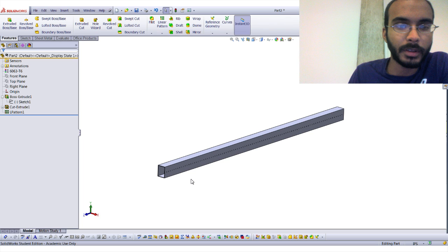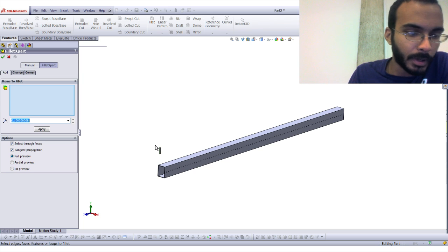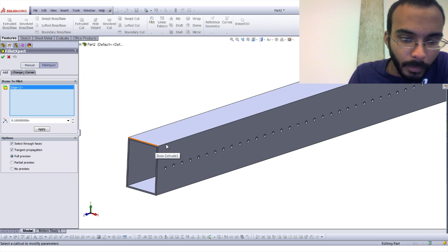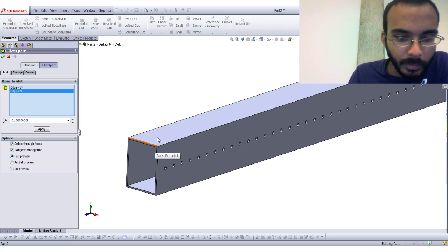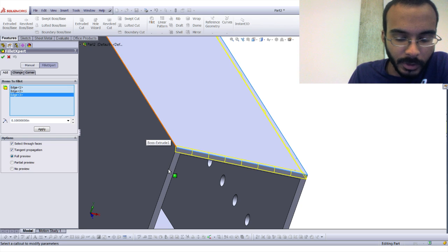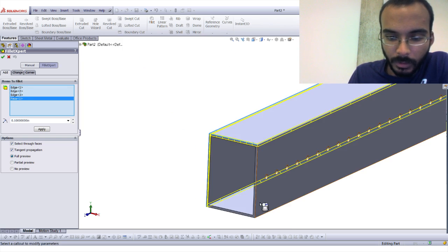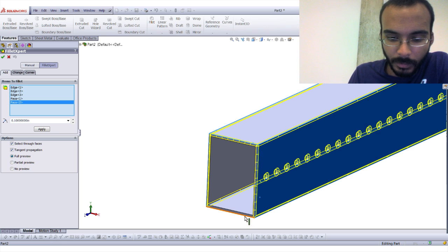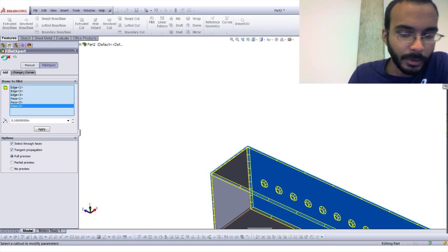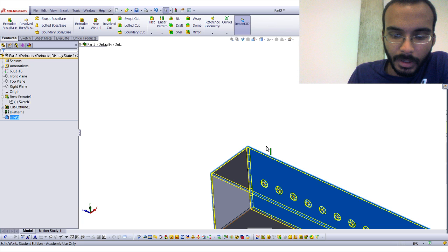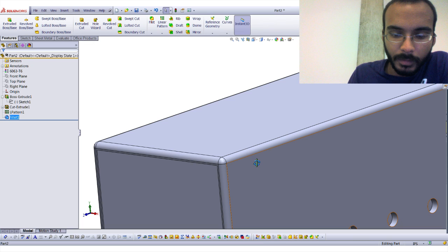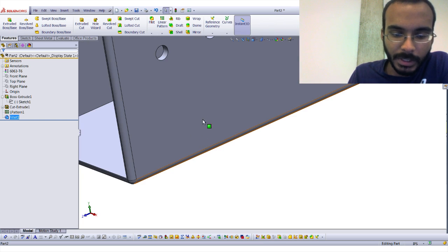Okay, so the other really useful feature that we'll use a lot is called fillet. So we had sketch fillets before, but now we can select many different edges on a three-dimensional part, and you can tell them all to be the same dimension. You can select whole faces, and it'll select all sides of it if you want to, and you can make nice rounded corner bits, especially on parts that are going to be sanded and things like that.